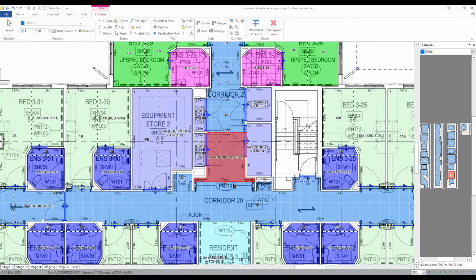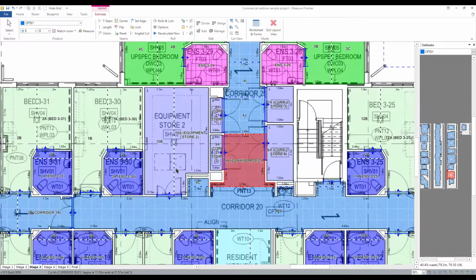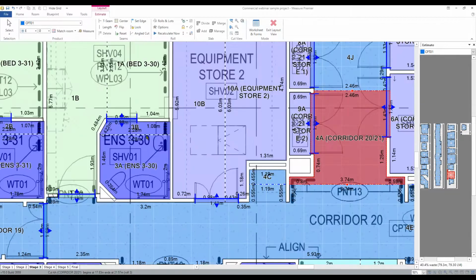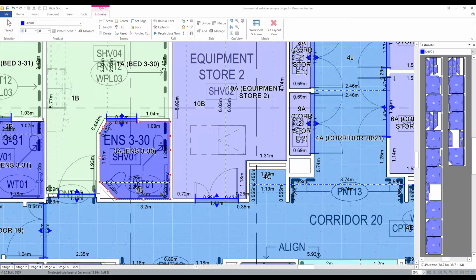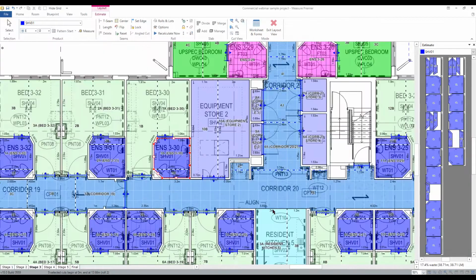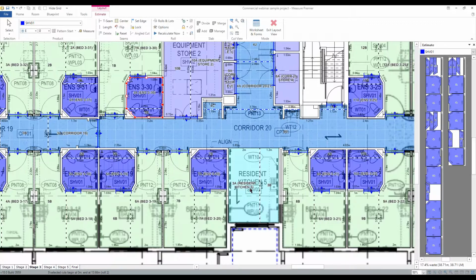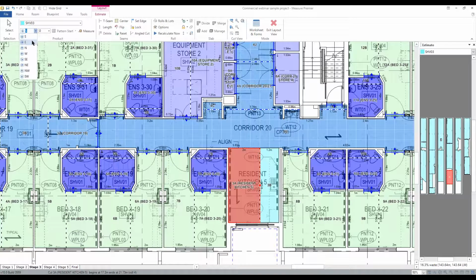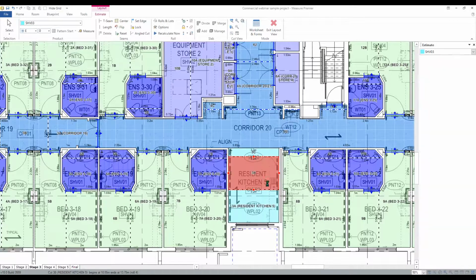Okay, so let's say we go through, we double check all the seams on all the rooms, we adjust them, we add some new ones. Sometimes, like maybe you just want the seam quickly on the other side of the room, you could right click and go flip. So there's some tools that make it quite quick to move through the plan and adjust the seams. Maybe this is one where we would want to rotate that to run east. We don't want joins running into the division there, and then maybe we want to flip that one as well.